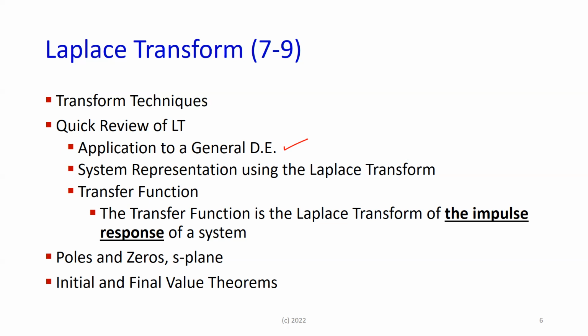So in some cases, while in the Laplace domain, or what we call the S-plane or the S-domain, you can see certain things about it. First off, from the Laplace transform, we got the representation of the system, and we got something called the transfer function. The transfer function, remember, is the Laplace transform of the impulse response of the system. It has a numerator and a denominator, all of them functions of S in the S-plane.